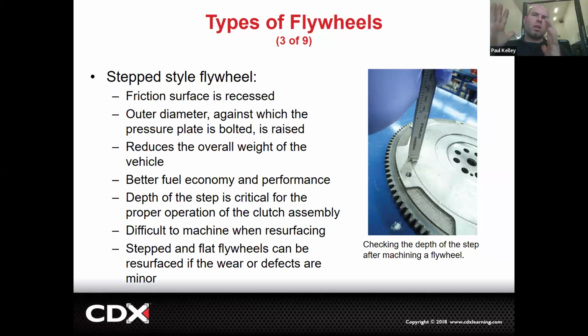Now you push the pedal down and the clutch disc is like, yeah, I'm kind of freed up, but I'm still sort of dragging across the surface, which means the disc doesn't stop. The disc continues to try to follow the flywheel at least a little. That's going to turn your input shaft a little. When your clutch is down, but your input shaft is turning, do you see how that would try to make the car go? It's going to be kind of like starting to stall out maybe. If you're at the intersection and you put it in first and you have your clutch pedal down and it's still trying to engage, it's going to drag you into the intersection.